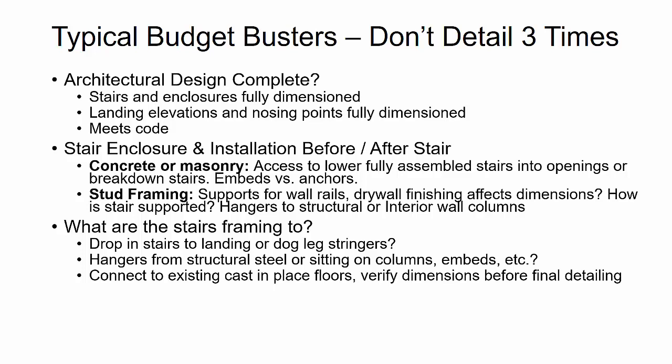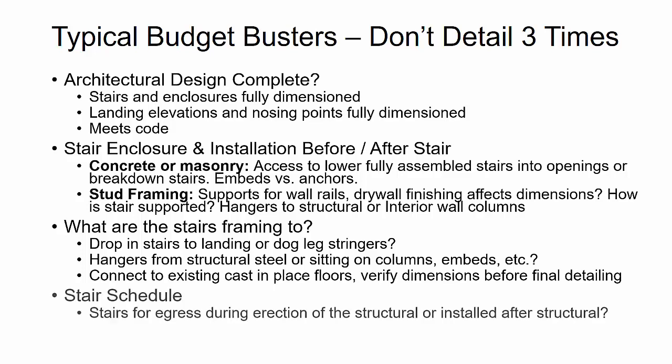Almost always near the stair towers, there's something that differs from the design, and you want to get as-built information and dimensions and make sure that your stair detailing is going to match that so that we don't have to redetail multiple times. Then lastly, understanding the stair schedule. Part of this is what is the enclosure, whether concrete or stud framing, but really understanding the stair schedule. If the structural is going on at the same time, in some cases, some stair towers are actually used as egress during the erection process, or during the job when they're actually doing things.